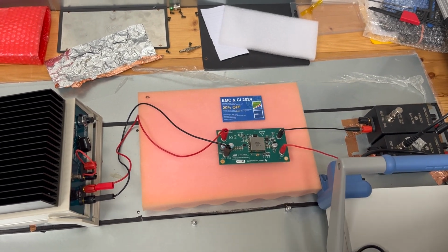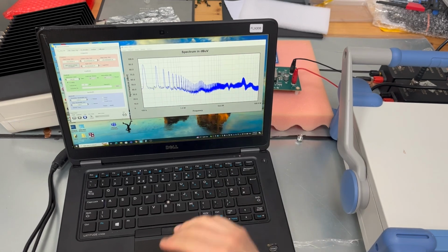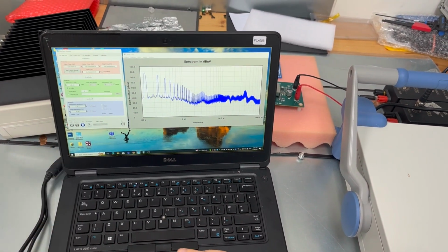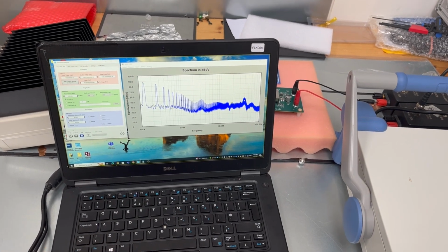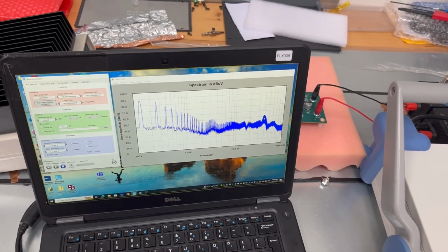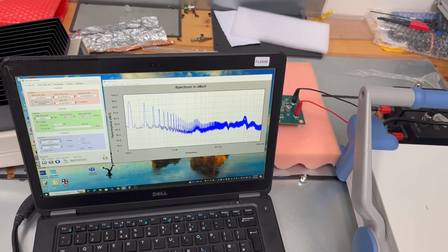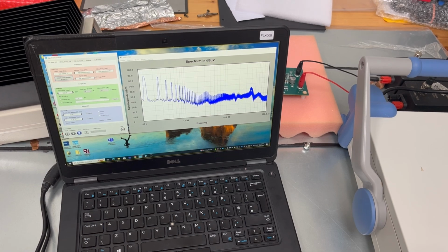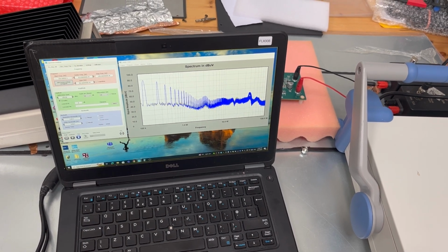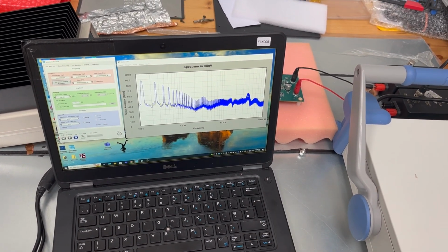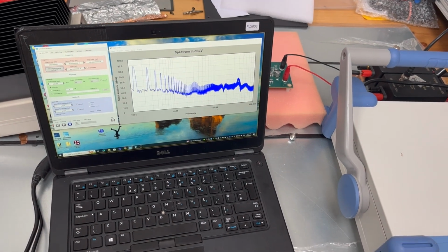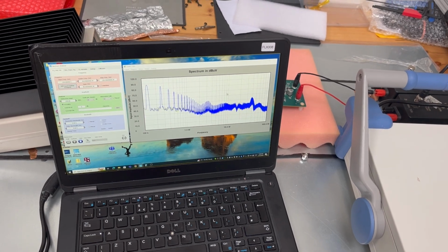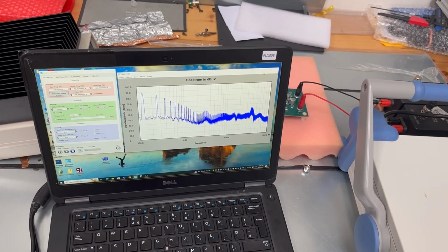Okay, so going back to our short wire, now let's have a look at the resonance phenomena, but in time domain. So I switched it on. Of course, it's back to where it stood previously. So again, we have a 40 megahertz resonance. Now some people were struggling to correlate this 40 megahertz phenomena to how the setup behaves. Well, most of us design engineers are familiar with time domain. So let's quickly switch to time domain and see what happens there.